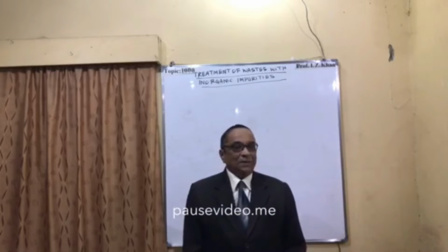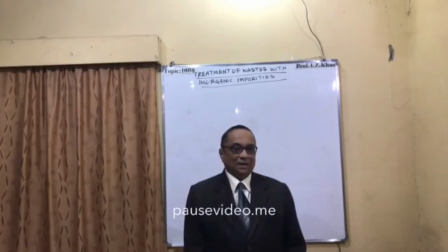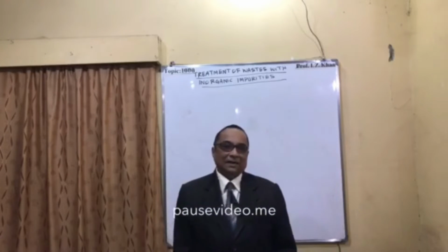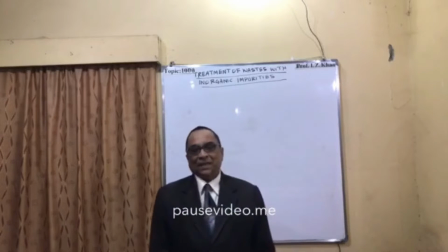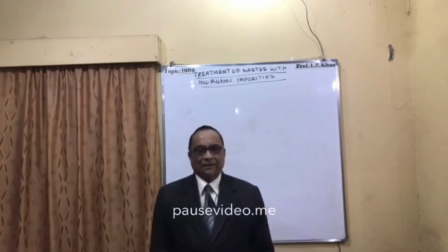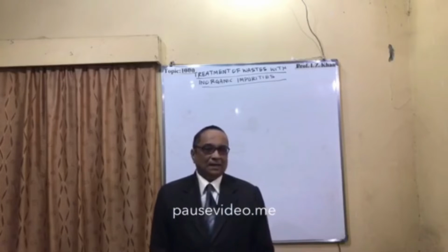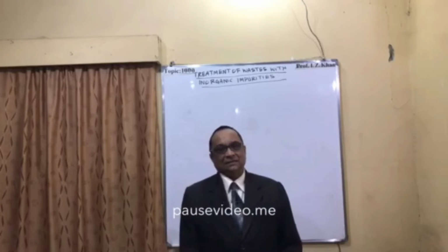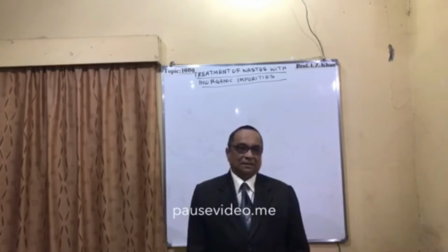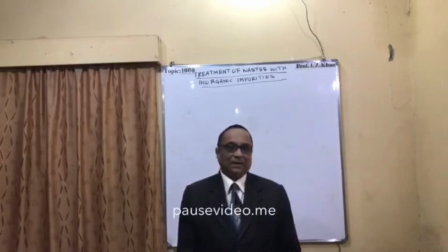And the maximum tolerance concentration level globally accepted should be in the range of 6 to 9 pH, means slightly acidic, or it should be alkaline, because 6 means slightly acidic, 7 is neutral, and 8, 9 is alkaline, and this range is accepted.